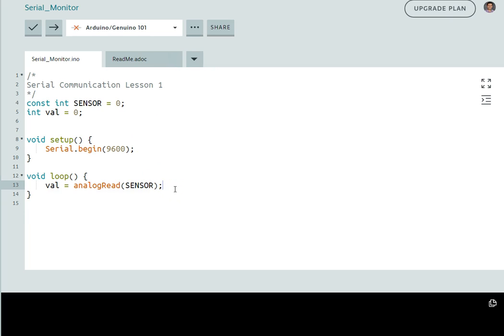Okay? Then, for us to essentially make our Arduino write out this information so we can see what that sensor is actually saying, we can use the command serial.println. We're printing the line of val. Okay, and we'll write a delay in there, a delay of 100 milliseconds. And that's all this is for this program, but what's going to happen is we connect the photoresistor.